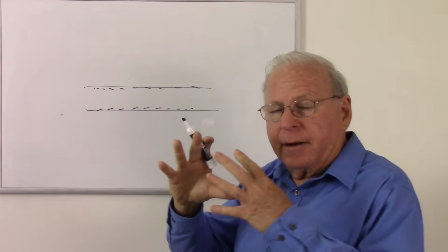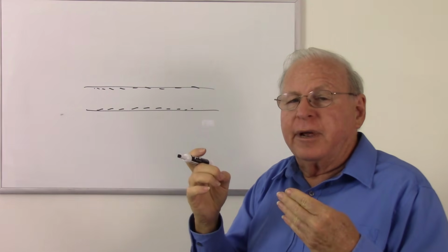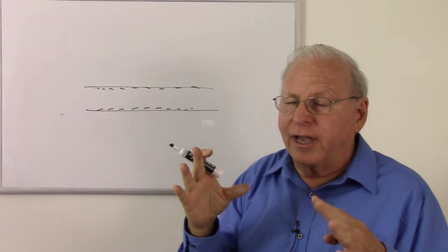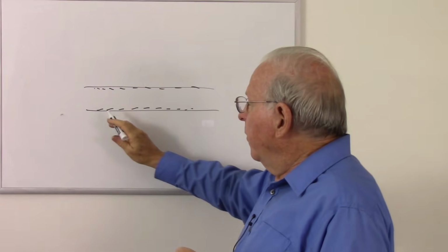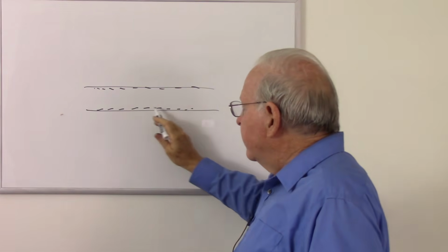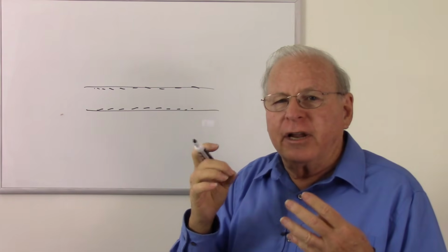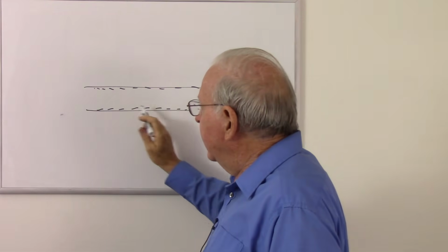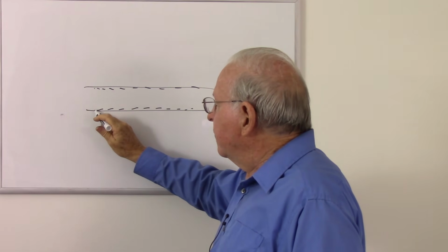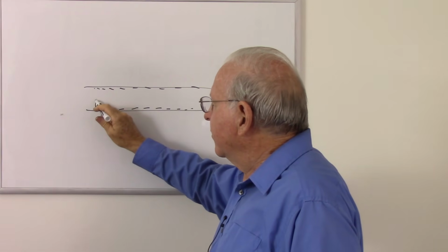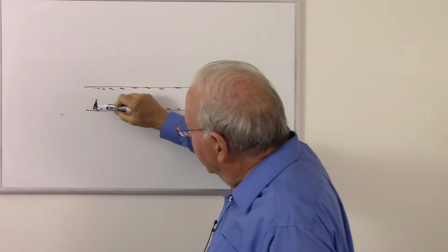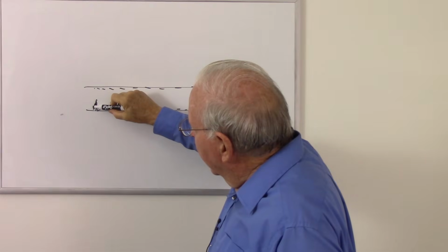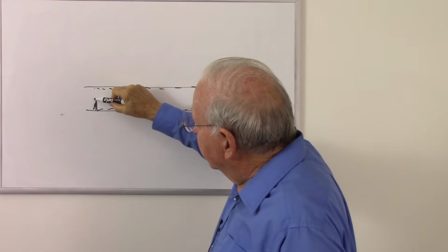And then I'm going to heat it up and melt that soot and it becomes pure germanium oxide and silicon oxide of the right proportion. But I'm going to have that first set of gases give me a little higher index of refraction. And I'm going to do that again and again so that my index of refraction starts out low and gets higher and higher. I don't know how to illustrate this, but low index of refraction, higher, higher, higher, and of course in the middle it's the highest index of refraction.